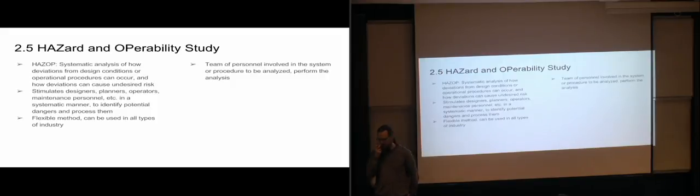So a HAZOP team will be set up, made up of personnel involved in the system, the design of the system, or the procedure that is to be analyzed, and they perform this analysis. It is important to know that the team will include both the people that are planning and designing and the people that are going to be using and performing the work, so that all of the chains and links are together in this analysis.